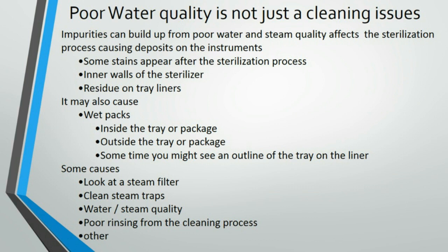It may also cause wet packs, right? We want good dry steam. I've always thought that was an interesting term, but it's true. At the right pressure and temperature, steam is dry, and it dries easier. And so if you're having water quality issues, that can totally affect that. It can affect inside the tray or package. It can affect outside the tray or package. And sometimes you might see an outline of a tray on the liner. That really meant that it was wet, and that was kind of dripping down, and the liners just picked up the outline of it.